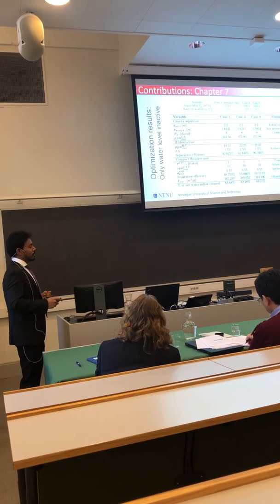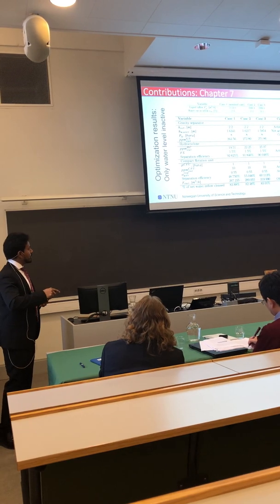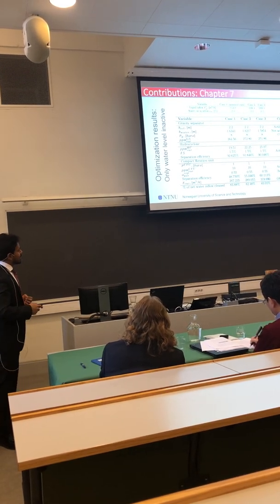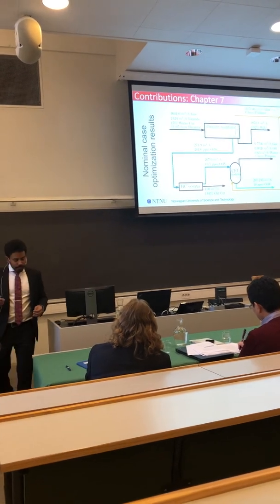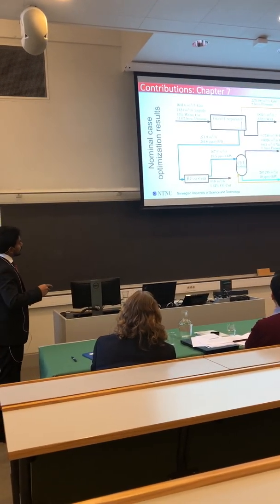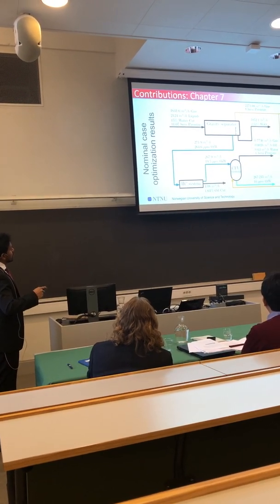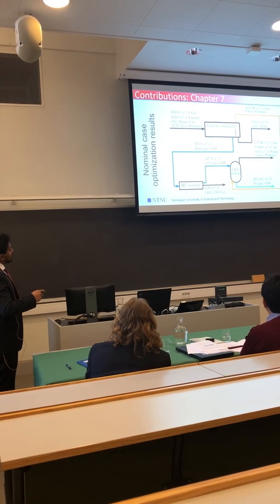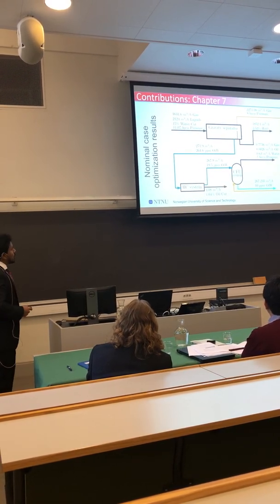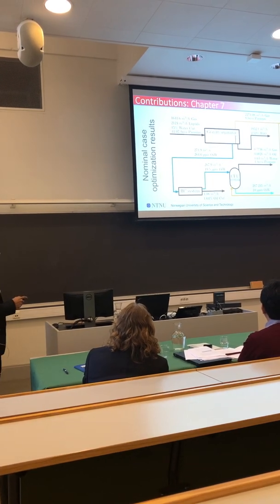Case number 2, we have a lower water that we are able to throw out, and in the 3rd case we have more water overall coming in, so this number goes a little bit higher. To put it in a nice way, I put this flow sheet where we have the gravity separator, hydrocyclone system, and the CFU system. These are the disturbances to the system. I consider an 11 bar inlet. It's very low, but I can argue about that later.